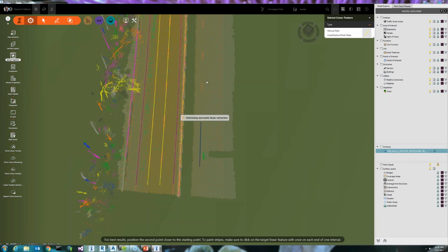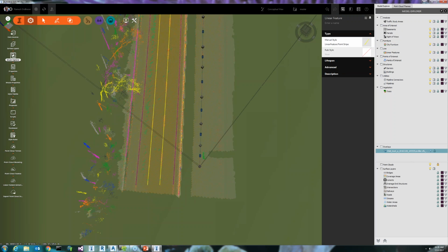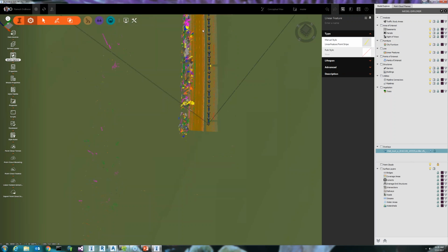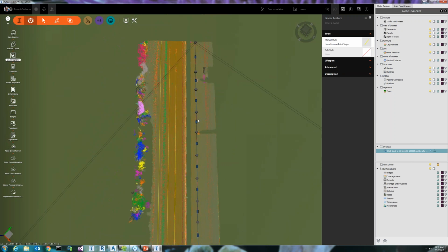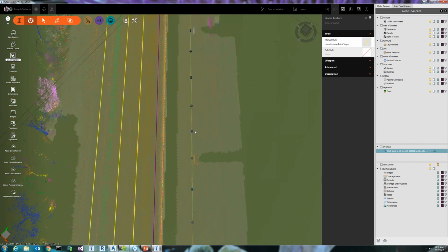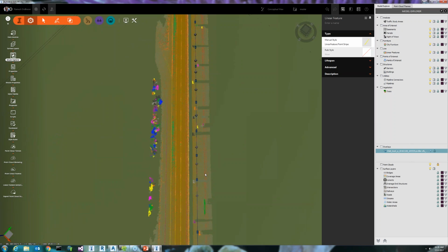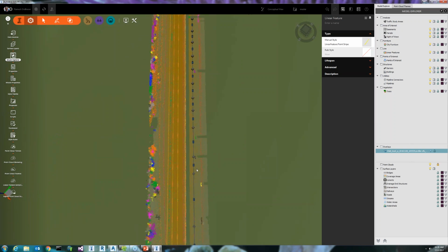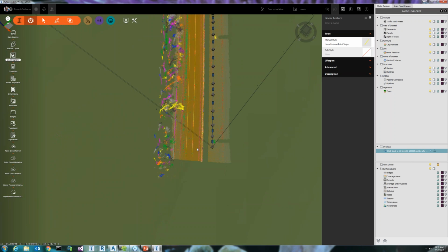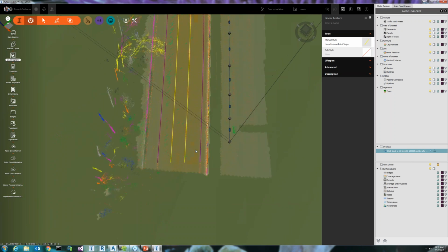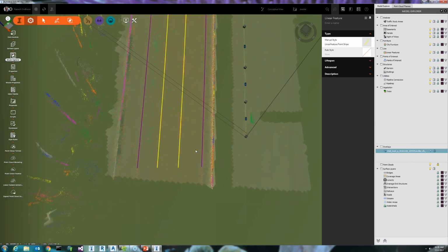If I'm going to extract some design work, some line work, it's better to get that. Right there, you can see it did the whole file again. There's my paint stripe. So it did a decently good job, a very good job on extracting the paint stripe part, which solves most of the people problem. When you want to extract the line work from point cloud data, whether drone or mobile or anything, extracting the line work is a tedious process. You have to manually do stuff. This helps you a lot.